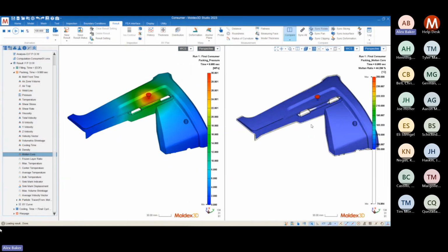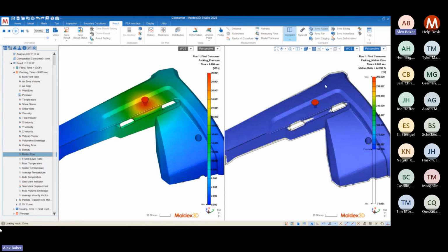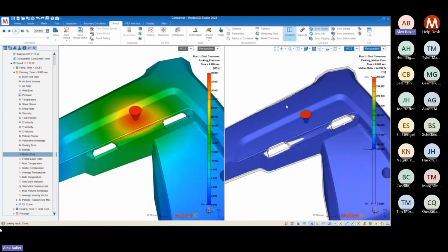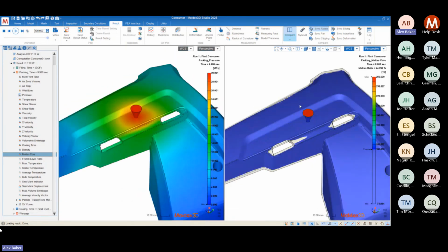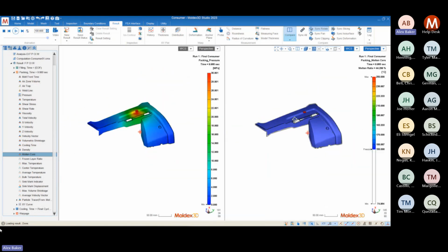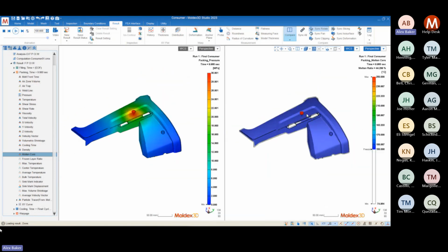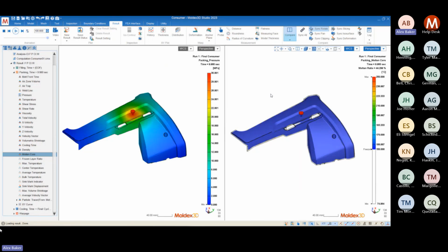So it's always a trade-off as far as how you want to handle your processing, how long you want to be applying the pressure versus how long you want the part to just be sitting in the mold, cooling off and getting ready to eject. All right, but this is something that simulation can evaluate, and it's something that we typically do take a look at very intensely.